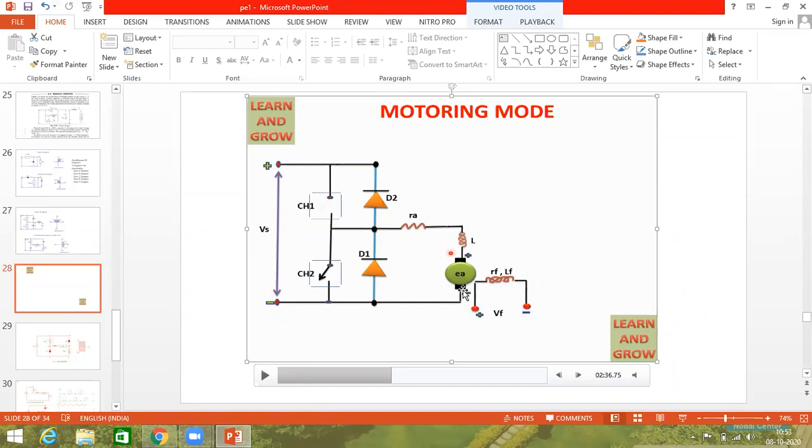So now how will it happen? During this condition, the back EMF is greater than the inductor voltage and the back EMF is greater than the supply. Therefore, the direction of the current starts from the plus terminal of the motor. You can see here they have given plus and minus, the positive terminal of the motor. So we can use the word generator. So G plus to inductor, and from the inductor to where does it have to go first? First the inductor has to energize once again. When the motor is acting as a generator, energy first travels from the generator to the inductor, and from the inductor, now that chopper 2 is on, the current flows through the motor. So we'll see the animation. Case 2.